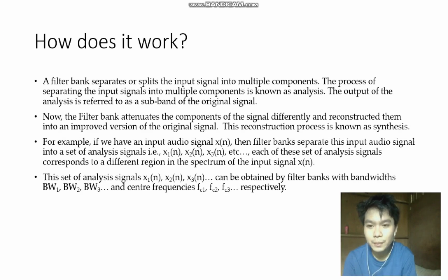The process of separating the input signal into multiple components is known as analysis. So the process in a filter bank that splits the components is called analysis. The output of the analysis is referred to as a subband of the original signal.